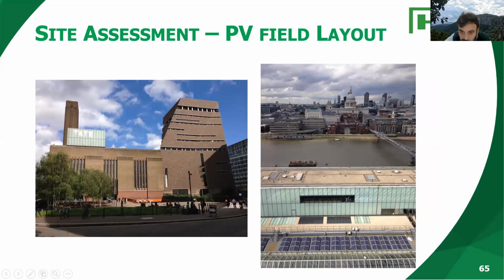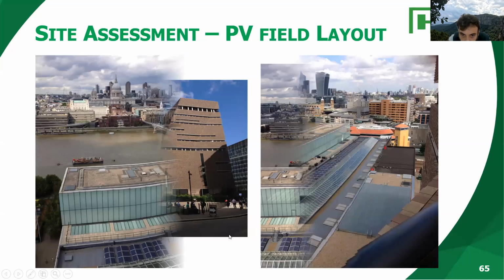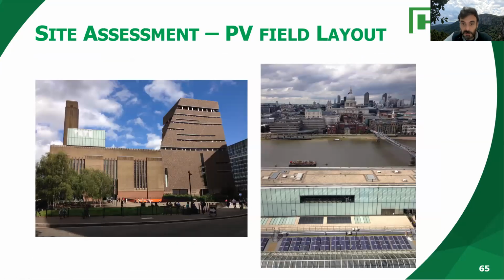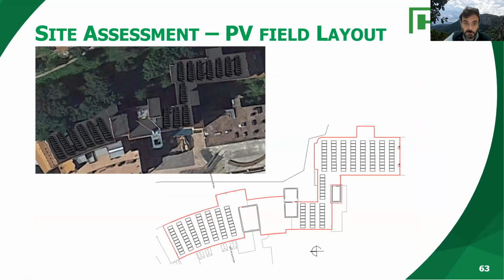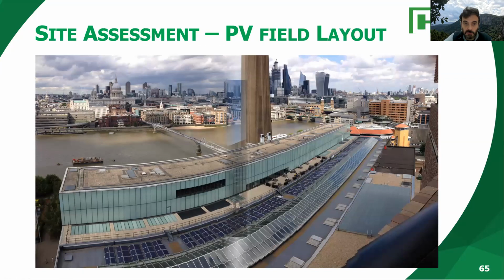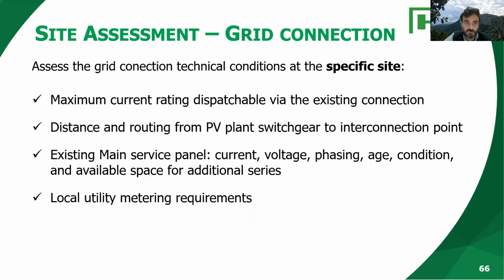And you can see the PV panels are very close together, so there is no need for that much spacing compared to the layout of PV panels in rows. Okay, so this is another tip I'm giving you when we design PV systems. What other things do we need to worry about?